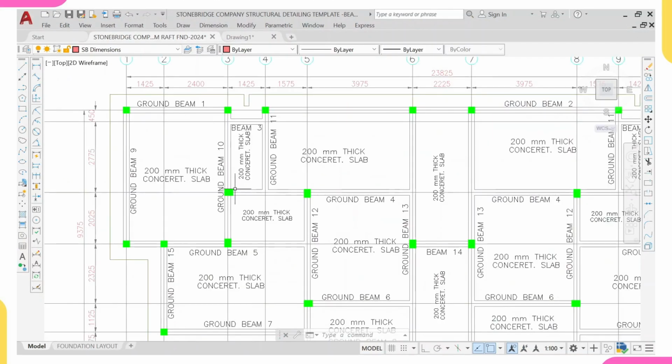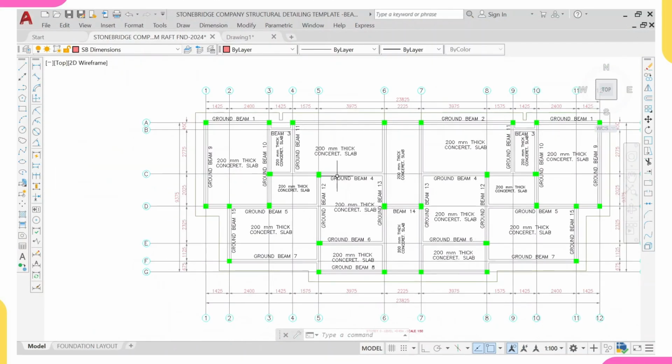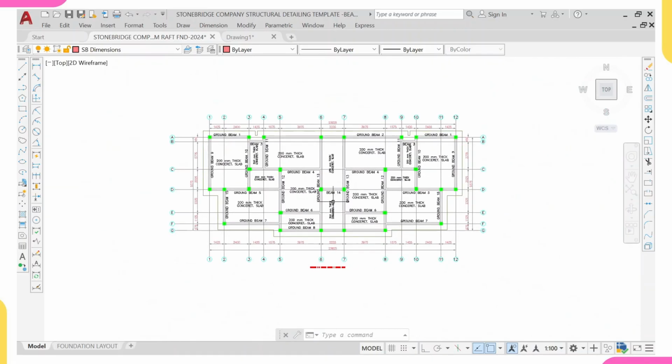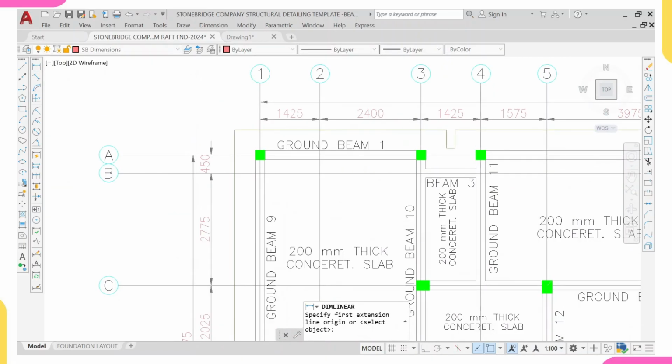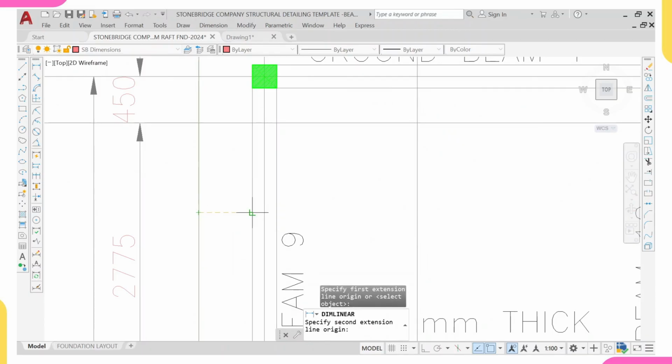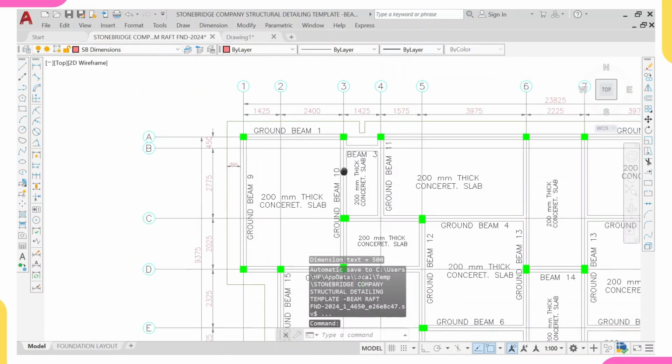So right now, I'm through with it. If you can see, all my inner columns are 225 by 300. Yeah, 225 by 300. So the next thing to do now is to dimension this cantilever length. From here to here, you know what it is now? It's 500.